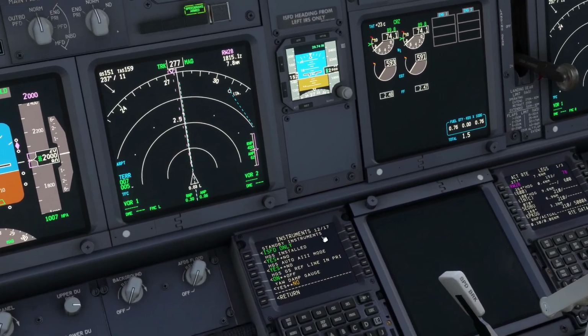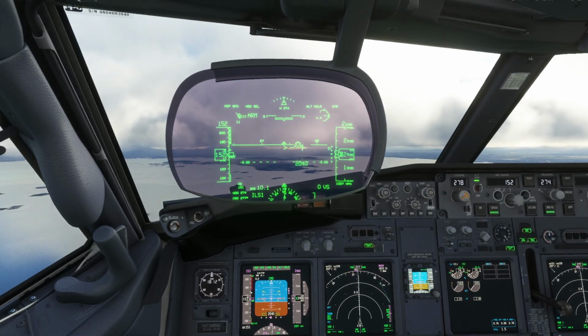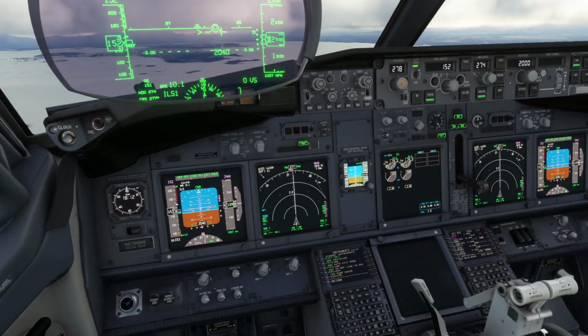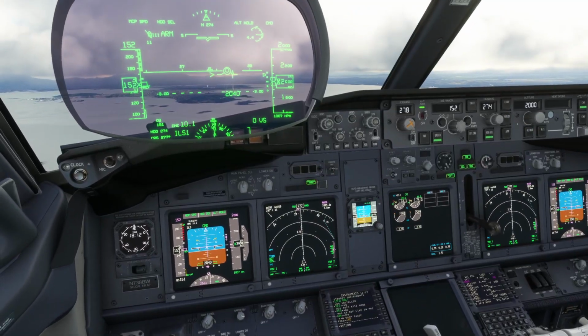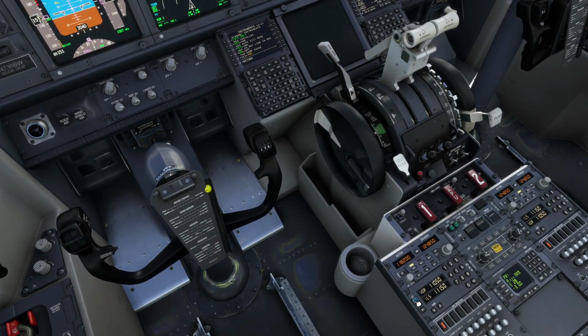So once again, the option to on, and the line is there. As you can see, we have AIIGS Auto Alpha 3 mode as yes, and you can see on the top here that Alpha 3 mode is armed. Okay, so that's what the second option does. Okay, basically that's it. I'm going just to remove the ILS from here.